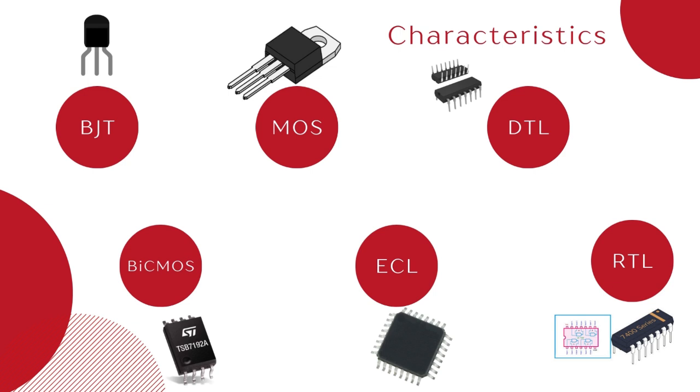ECL is typically used in high-speed computing, telecommunications, and signal processing applications where speed is a critical factor. While ECL is the fastest logic family, it has low integration density and is not suitable for power-sensitive applications.